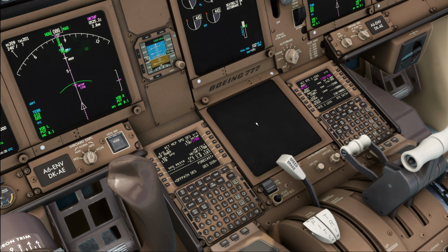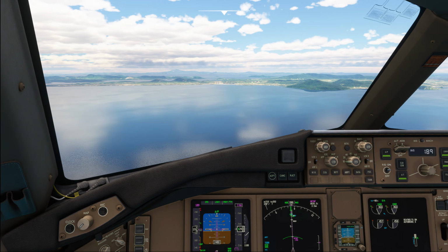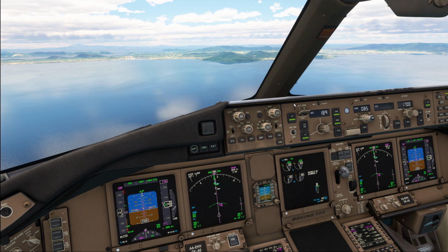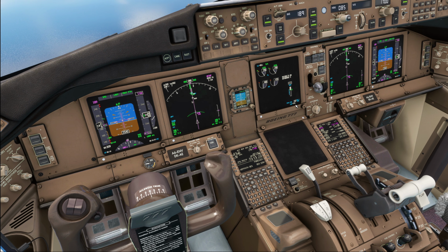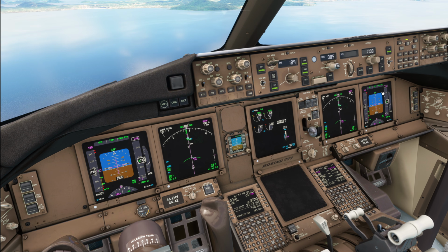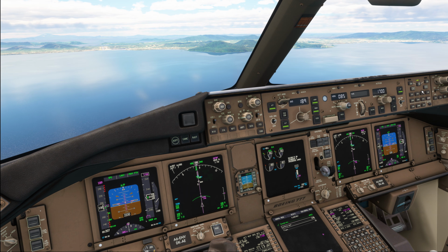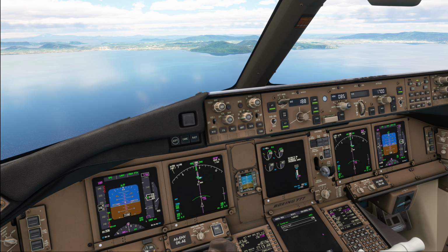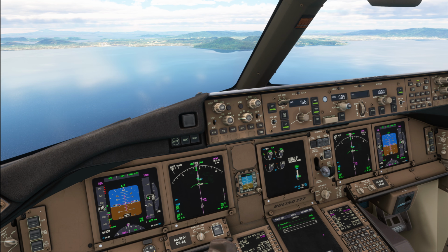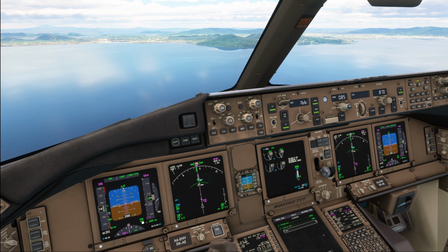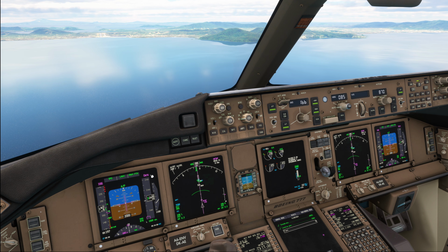Now, since we do not have a runway waypoint today, we have to turn the flight directors off once visual references are established, and we are going to switch on the pilot monitoring flight director again, so that we are prepared for a go-around. More on that in the go-around tutorial. Okay, so we're 2 miles prior to the FAF. I'm setting the altitude down. And as you can see, since I've set a minimum of 870, we're actually able to set 870 on our MCP as well.